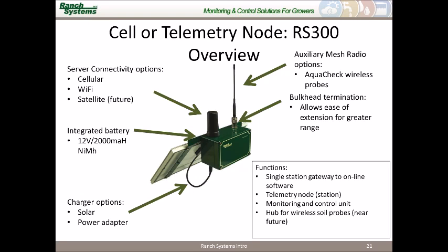And for doing irrigation control, it's a good idea to evaluate the full system and look at this. But a good starting point is an RS-300 cellular unit if you're just getting started with it. But if you have plans for expansion, it is a really good idea to go with the RM210. And the reason for that is the RM210 can provide connectivity for multiple stations, has a lot longer run time, and can do more of these advanced control and monitoring scenarios.